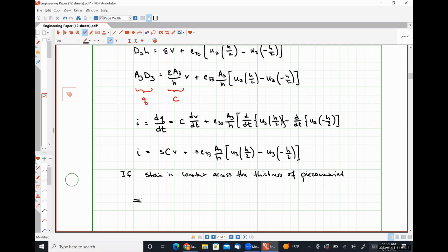Can you please explain the previous slide? Okay. So this S right here is the Laplace operator S. When we take a derivative in the frequency domain, it's the same as multiplying by S. We actually talked about this before the break when I introduced this previously. For a steady state sinusoidal system, S is J omega.